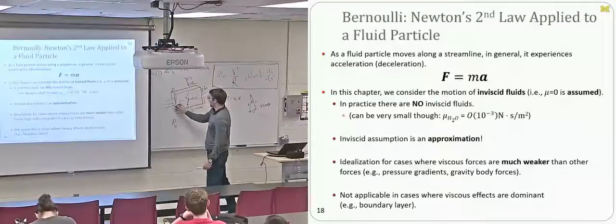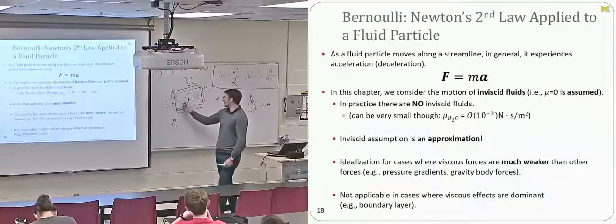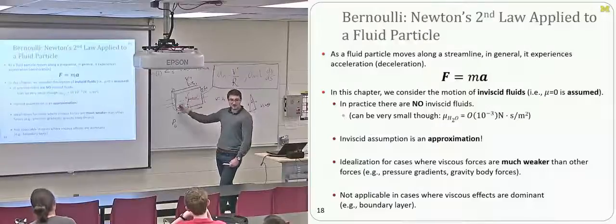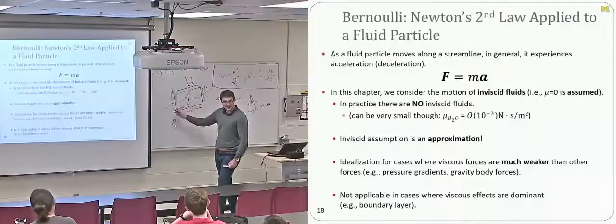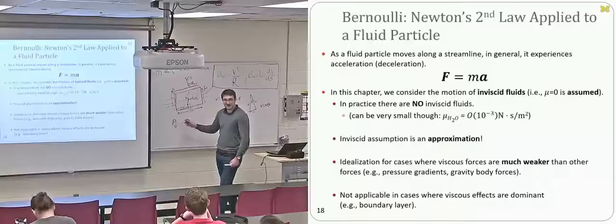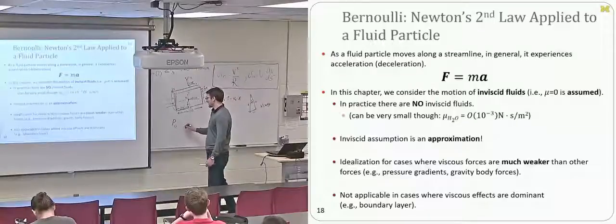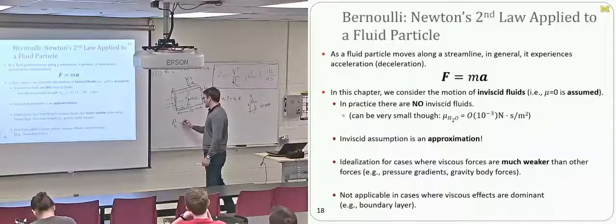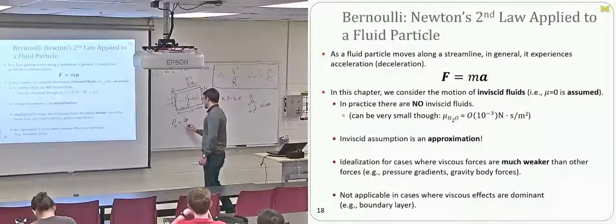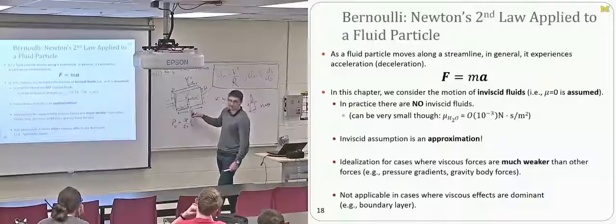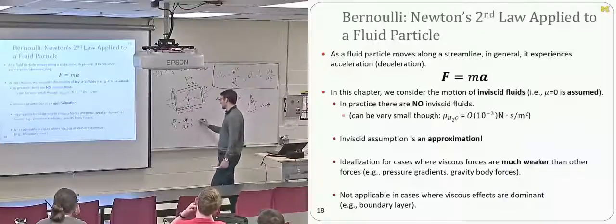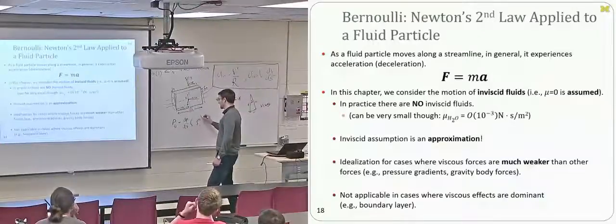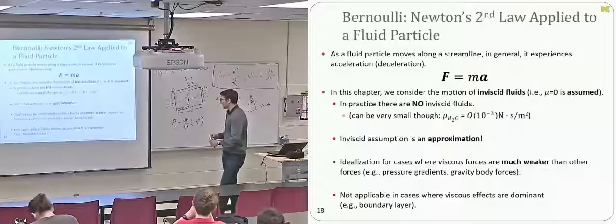However, are we going upstream or downstream from this point, along the S or along negative S? Negative S. So we're going to say P naught minus, well, we can do plus dP ds, but then the distance that's traveled from this point is going to be negative ds over 2, right?